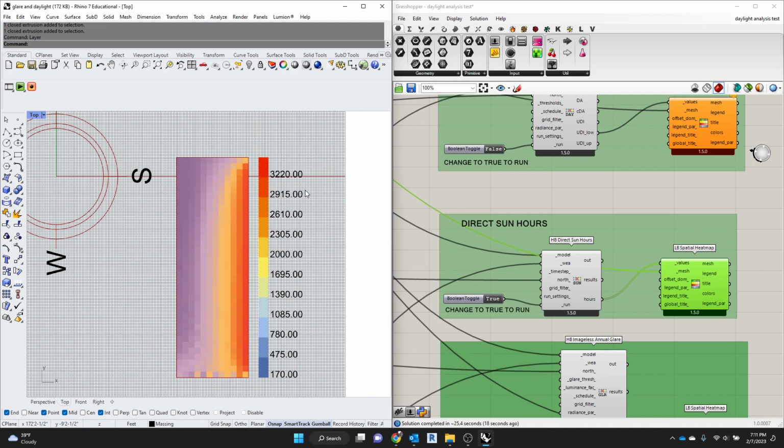It's penetrating a lot deeper into space. You were getting 1,600 just at the line of the facade. Now we're getting 1,600 hours, a couple feet into the building. We still don't have any sun back here, but you could imagine we don't have that because the building's deep, the windows are only so big. We would need taller windows and all that kind of stuff.